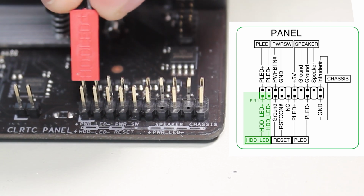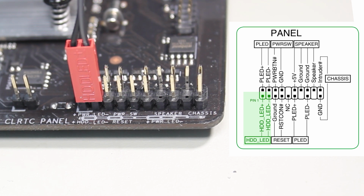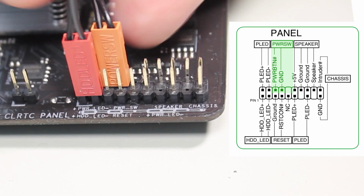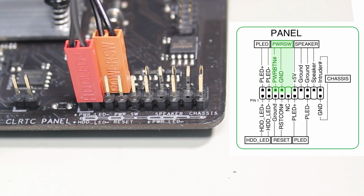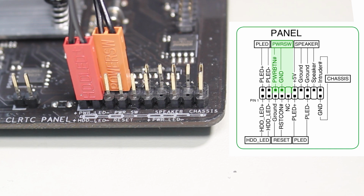Now all I need to do is connect the connector to the pin, making sure the positive and negative line up with the pins. The next connector that I will attach is the power switch. Since the power switch is a switch, it does not matter which way you connect it. In this case, the power switch is not labeled with a positive and negative wire. Generally, when in doubt, I will plug the connector in the same direction as the others. That is, the writing on the connector faces us, just like the hard disk connector. Although the manufacturer of the motherboard is free to put the pins in the front panel connector any way they want, they generally follow this trend of having the negative wire on one side and the positive on the other side.